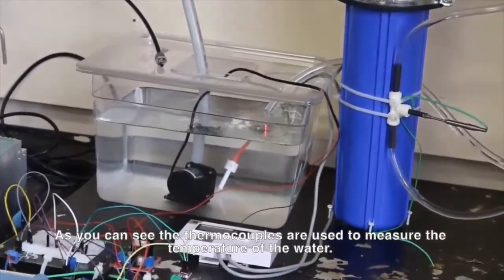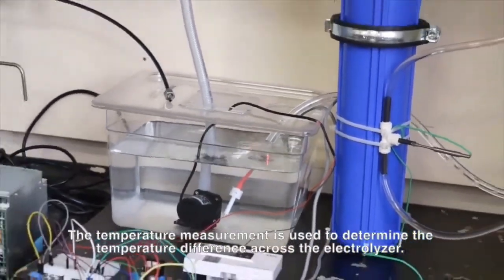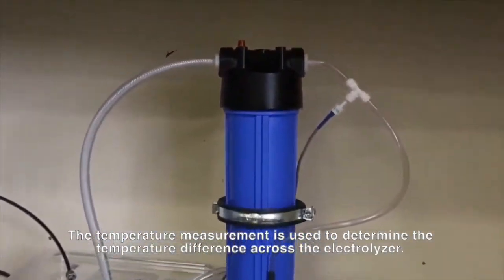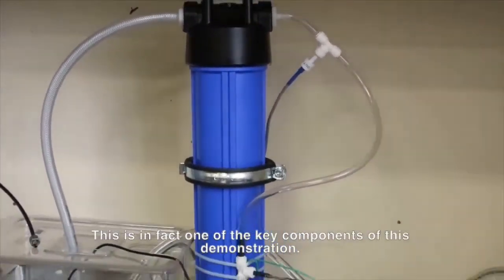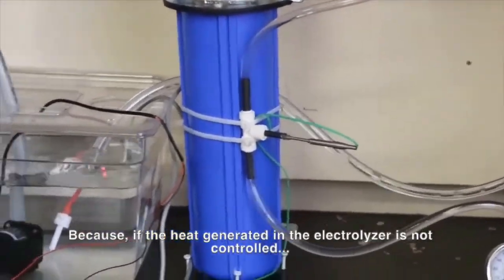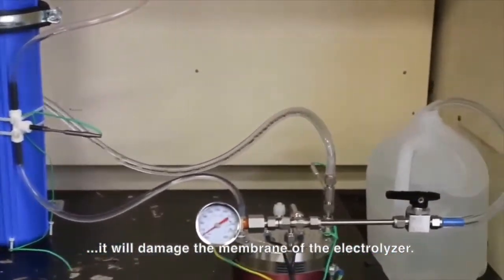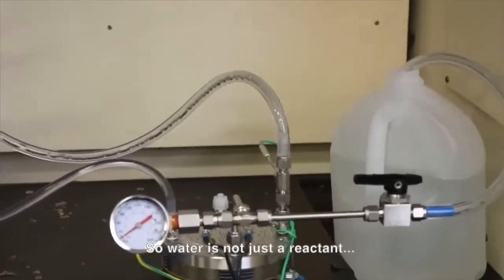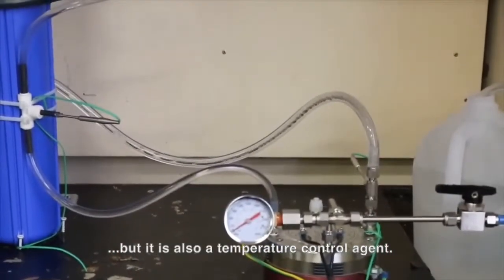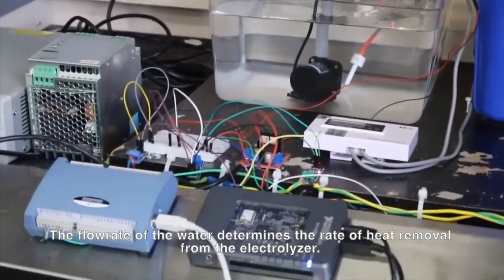As you can see, thermocouples are used to measure the temperature of the water. The temperature measured is used to determine the temperature difference across the electrolyzer. This is in fact one of the key components of this demonstration, because if the heat generated in the electrolyzer is not controlled, it will damage the membrane of the electrolyzer. So water is not just a reactant, but is also a temperature control agent. The flow rate of the water determines the rate of heat removal from the electrolyzer.